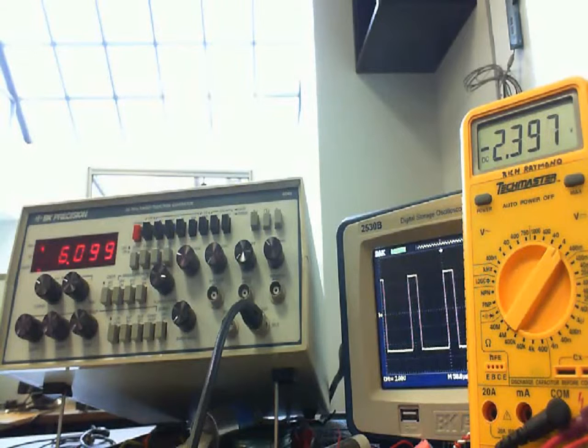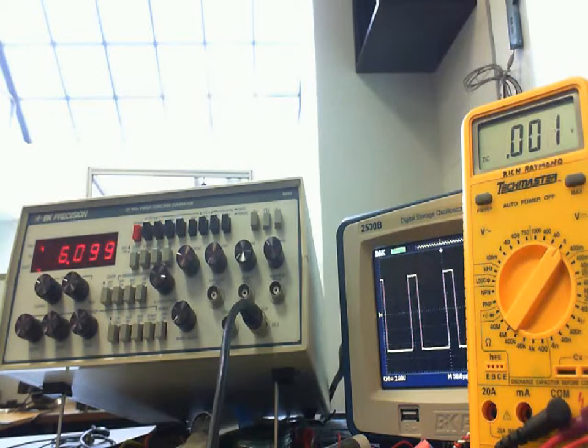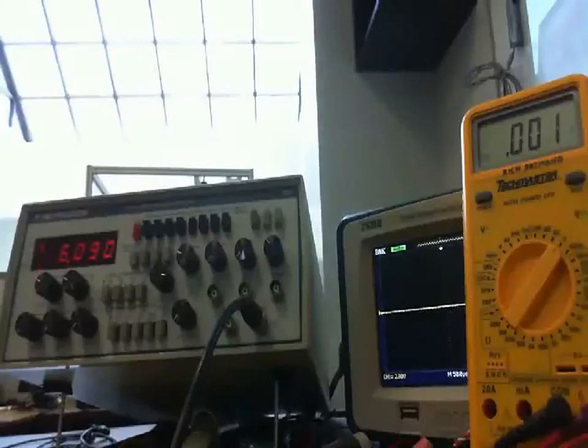So this is the problem with the DC meter. A lot of times we can tell things change, but we don't know until we get a device called an oscilloscope. So that's the advantage of an oscilloscope. What does it do? It shows you what's there. A digital meter is going to do what? It's going to give you an average of what's there. But a lot of times when you see it do that, you can get a pretty good feel. By the way, if the frequency changes, I wasn't changing the frequency, the meter would probably give me the same average, and we'll talk about that.